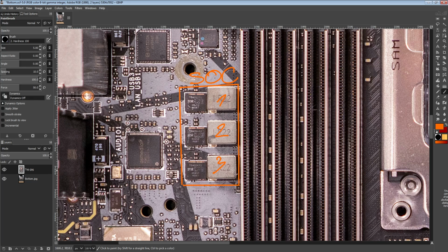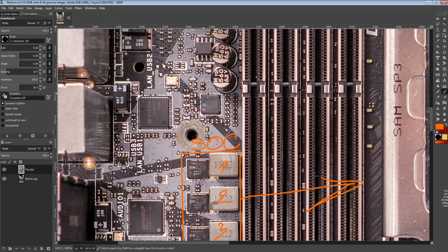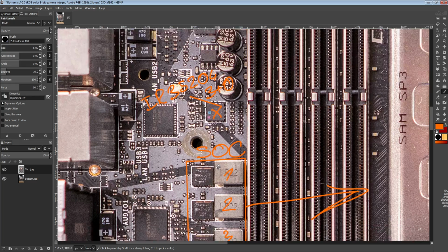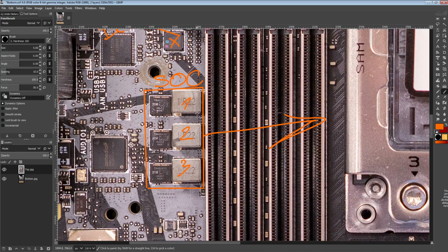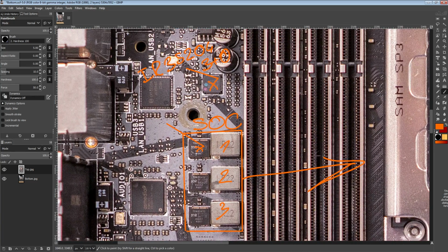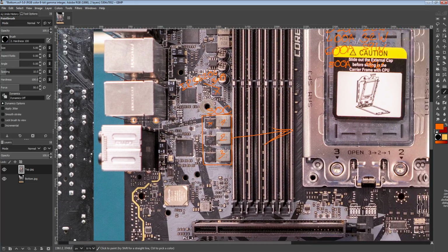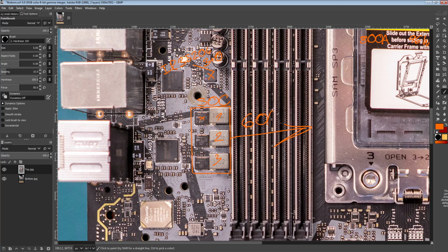And this is actually also very standard for TRX40 motherboards. Now, there are some where you have only a 2-phase SoC, especially at the lower price points. So this is a 3-phase controlled by a 35204 IR, of course. That's International Rectifier, which is the same thing as Infineon, because Infineon owns IR. It runs as a 3+0 controller right here, though it can go up to 3+1. And we've got more TDA21472s, more of those lovely 70 amp smart power stages, which does mean the SoC VRM here is capable of pushing, say, 60 amps while producing 5 watts of heat, which is nothing.